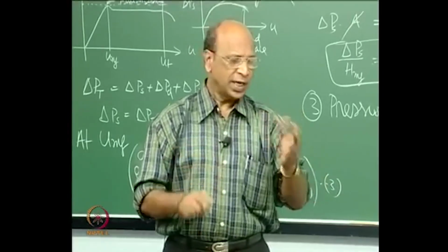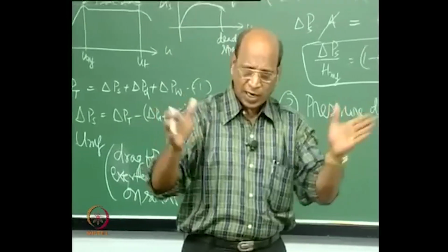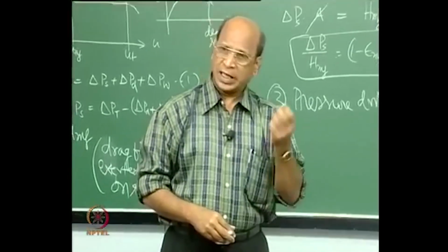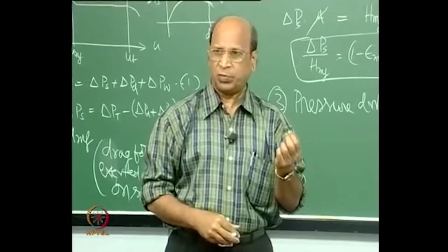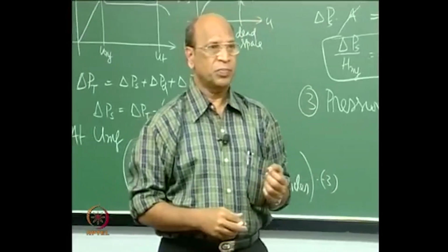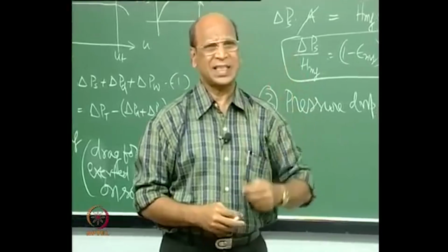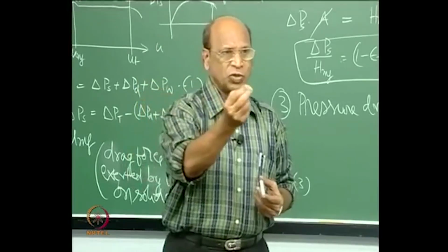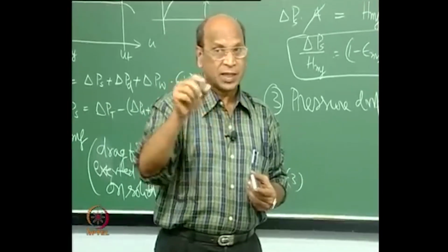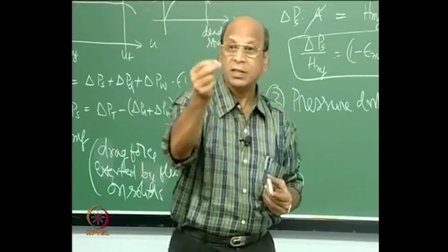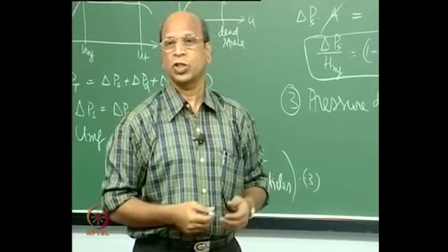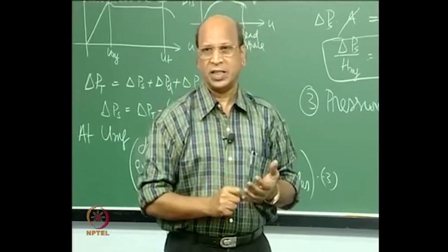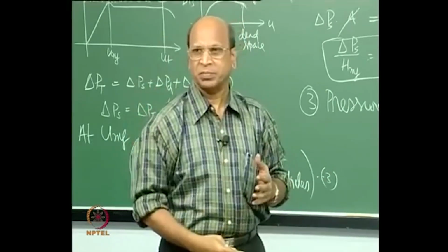Porous distributor, what they do is, they take very fine powder and then compress it as a plate. They use copper shots. Okay. They can also use lead shots, they do not use. Copper shots are very frequently used. Alumina, glass. You should have seen this. I think you would not have noticed it when you are doing physical chemistry lab, they use for filtration, sometimes not the filter paper, but sometimes they use the glass frit, they call. That is a porous distributor. Exactly the same thing is used, and that frit has a given porosity. You can ask for 10%, 20%, 30%. That frits.